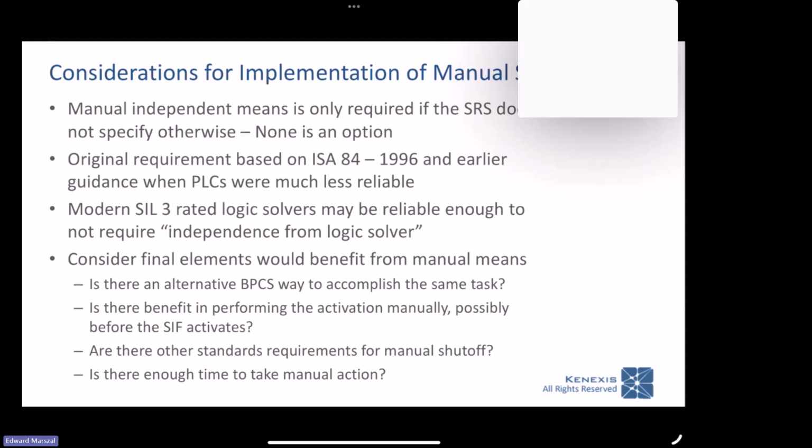If the shutoff valves connected to the SIS didn't shut, didn't go to a safe state, do you need to de-energize, or is it okay that you would just take the flow control valve or the pressure control valve that's supplying fuel gas to the fired heater, go to the basic process control system and put that BPCS valve in manual and set it to 0%?